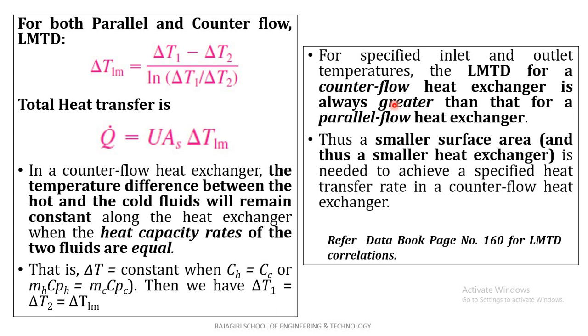So for a specified heat transfer rate, a counterflow heat exchanger is smaller in size than a parallel flow heat exchanger, or a counterflow heat exchanger needs less area for a particular heat transfer rate.